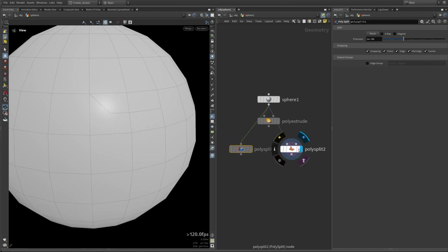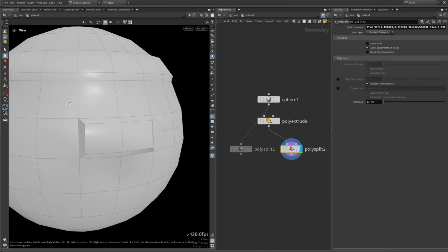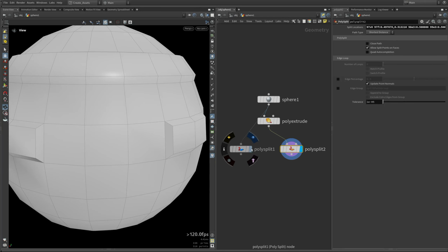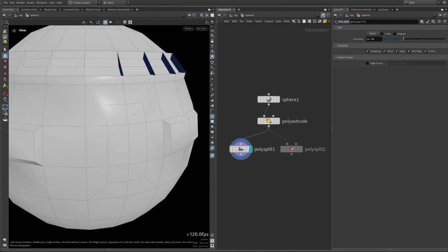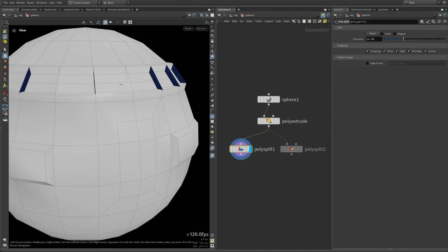Now I will show you the difference between PolySplit and the native Houdini tool. If intermediate nodes are included, the native tool fails to preserve the cut because the topological connection is broken. This is the key advantage of PolySplit over the native tool. It is topology independent. It stores spatial 3D data, allowing it to preserve the cut in the exact same location regardless of topological changes.